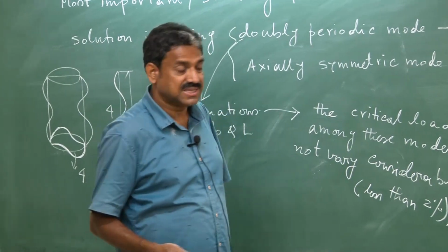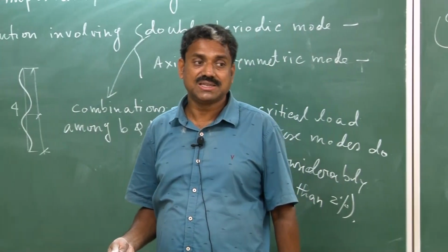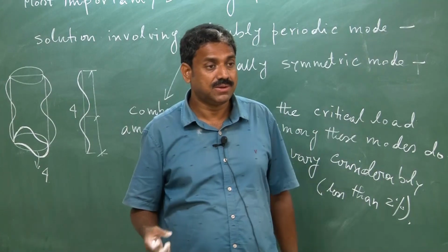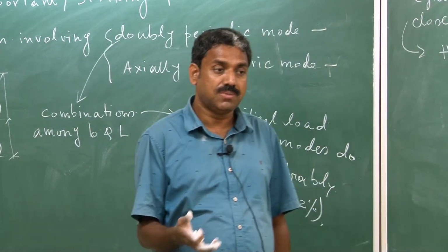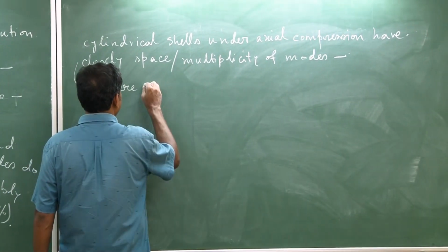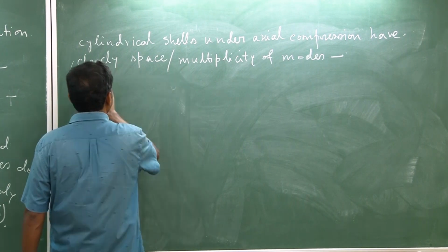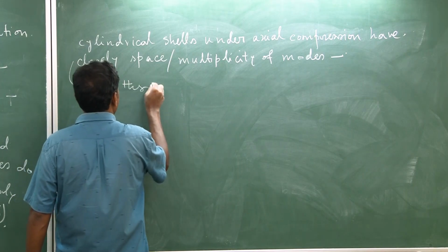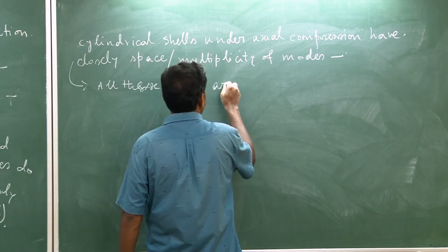I emphasize that we can linearize it, but the Donnell equation is nonlinear as well, because Nxx0, Nyy0, Nxy0 are always changing with incipient deformation, and there will be coupling. So, all these modes are geometrically coupled modes.